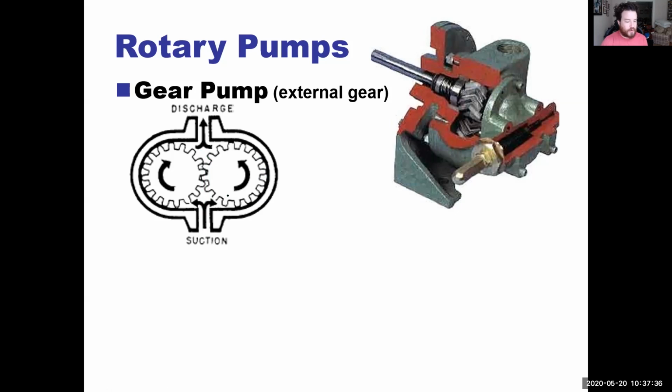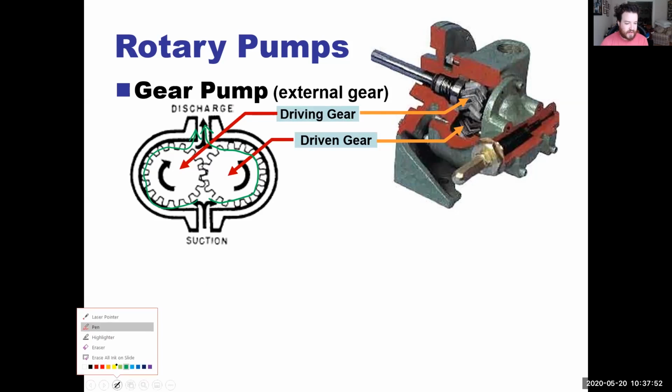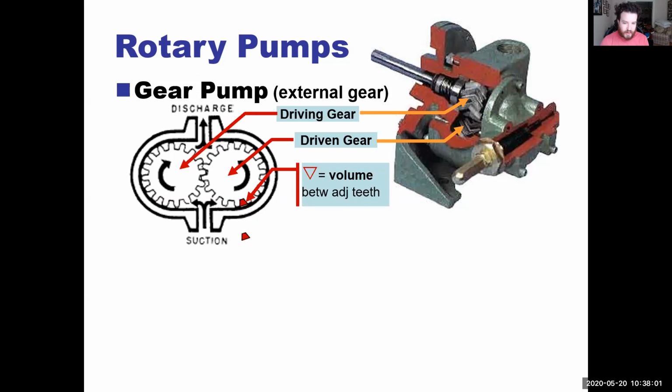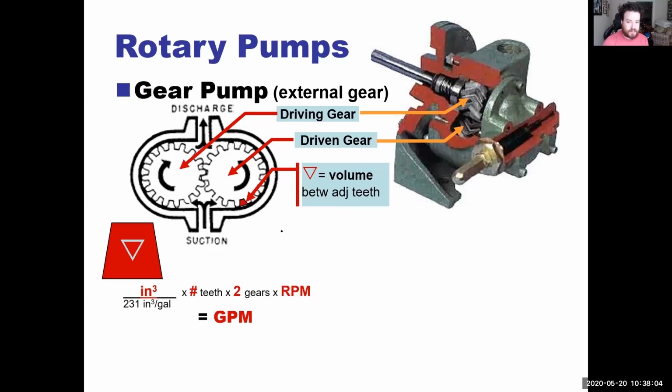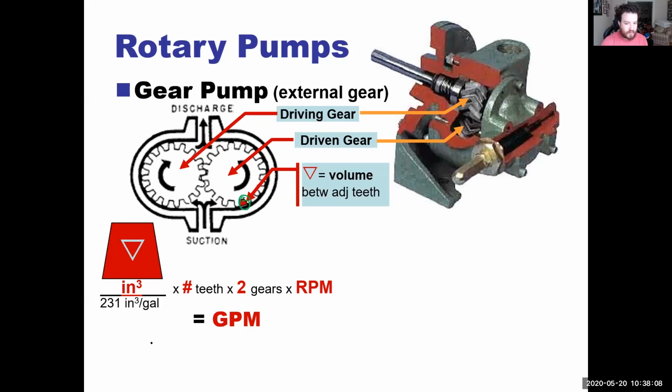So they have what looks like a wrong rotation, but they are going the correct way because the discharge is going around. These will have a driving gear and a driven gear. No sense having both of them being driven since they're gears. The volume is the area inside of those teeth.